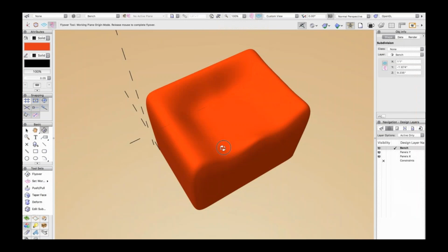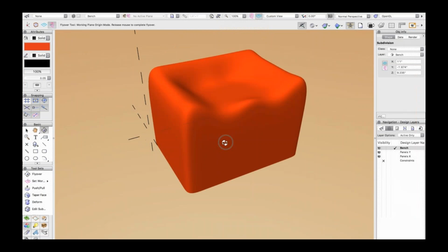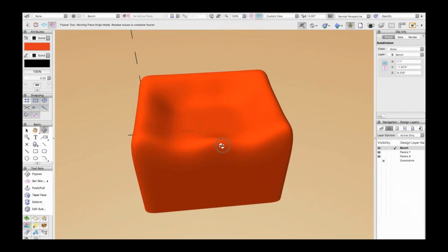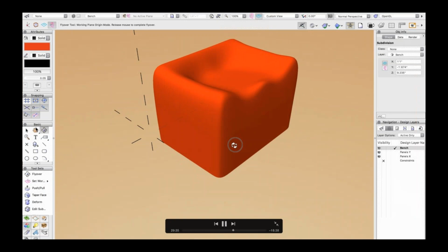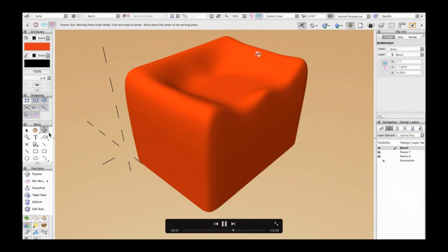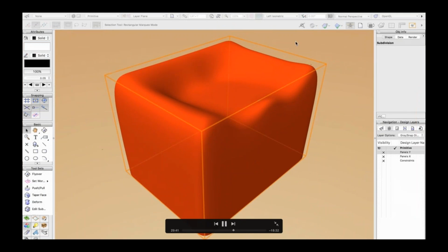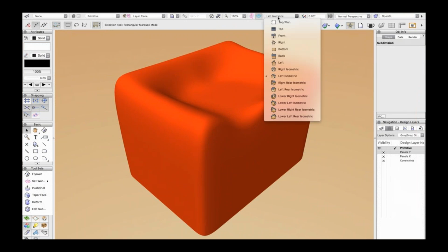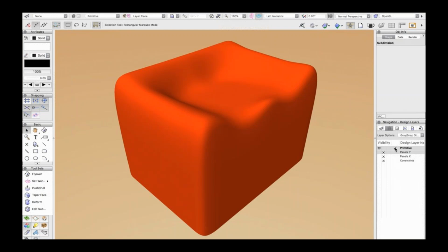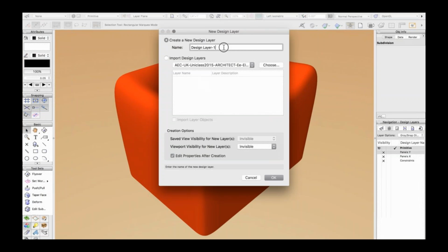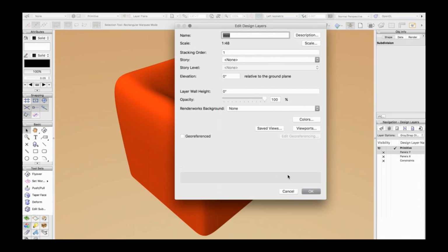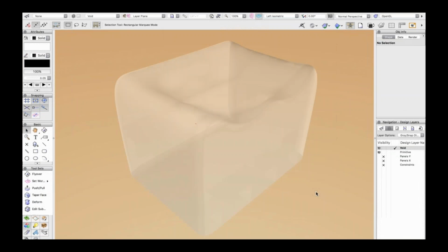And how I'm rotating around this particular object is using the orbit tool, and we'll see that here in the basic tool palette, and just click on that orbit tool or use the command Shift-C to orbit around it. Now here's something to keep in mind when you are using the orbit tool to fly around a particular object: it does deactivate the Edit Subdivision tool and requires you to go back into the tool or double-click into your primitive object in order to edit it again.